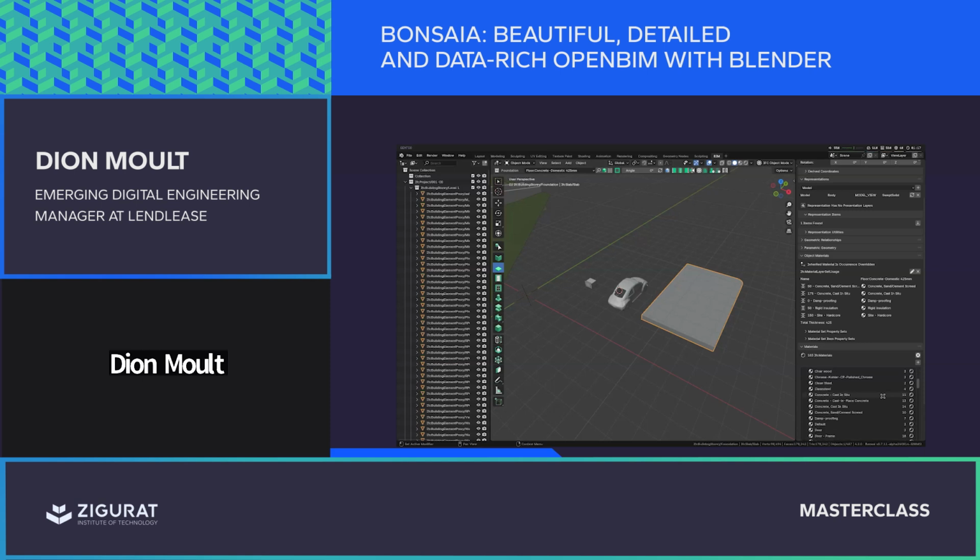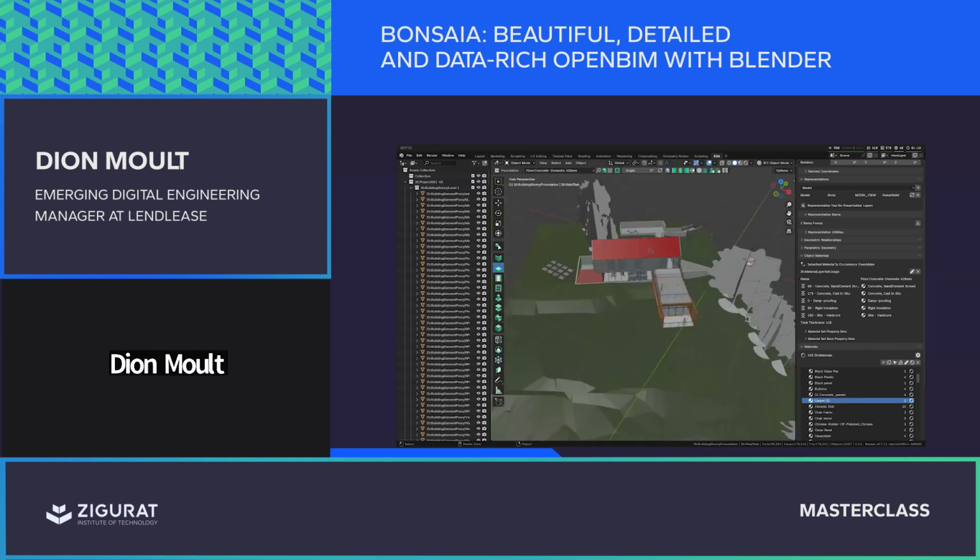We have a lot of, all these materials are uncategorized. So typically we should be able to break up materials into high impact materials like concrete, steel, aluminum, glass, timber, asphalt, things like that, which have high cost and high carbon impacts versus materials which have a less impact. But now you can actually see that. I mean, most IFC viewers don't show you this kind of material breakdown. So I can't, for example, find everything that's made out of carpet within a single click in the model.